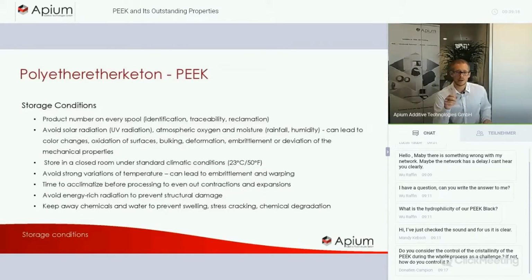If you do not have a dry filament, you can already see at the nozzle the formation of bubbles, and therefore you will have less material extruded out. The extrusion is not constant. You will face holes and voids inside of your part.